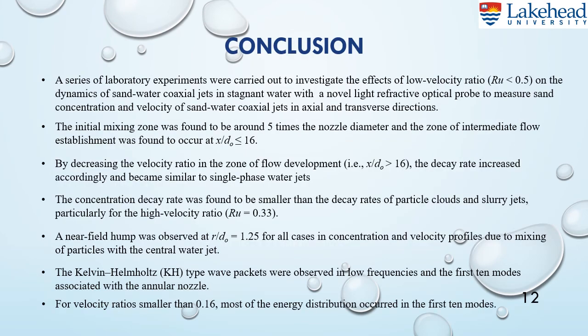And finally, the conclusion. A series of laboratory experiments were carried out to investigate the effect of a low velocity ratio on the dynamics of sand-water coaxial jets with an advanced optical fiber probe. The initial mixing zone was found to be 5 times the nozzle diameter. By decreasing the velocity ratio in the zone of flow development, the decay rate increased accordingly and becomes similar to the single-phase water jets.